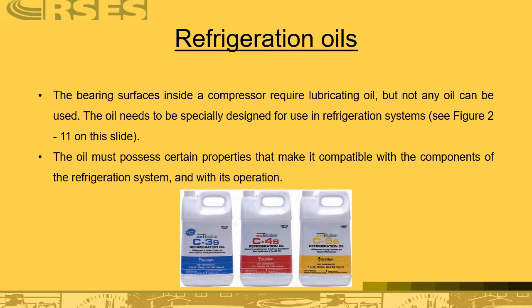If you look at those samples of oils illustrated in the slide below, you will not see the oil that is currently used in new compressors. It could be an alkyl benzene, it could be mineral oil, which has been phased out for the most part in new equipment. And as I said, POEs are always stored in metal cans.